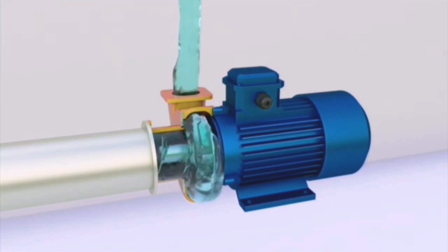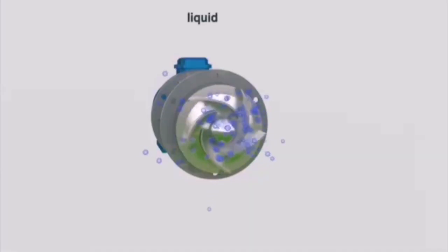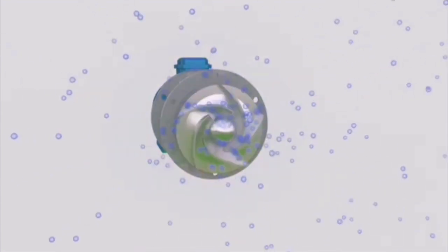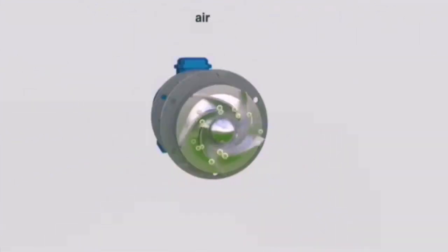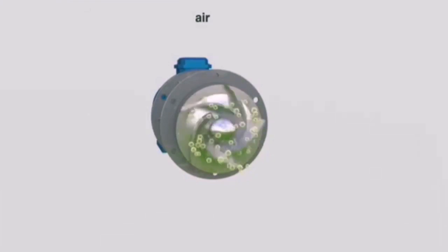There are three main types of impeller used in centrifugal pumps. Number 1, closed impeller with back and front disc. Number 2, semi-open vane with a free open front side, and number 3, open, which means free on both sides.